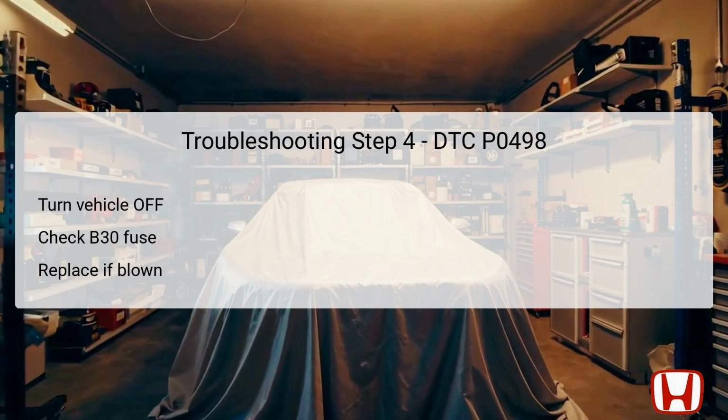If this fuse is found to be blown, replacing it is the immediate action required. However, if the fuse blows repeatedly after replacement, it is essential to investigate further for underlying issues, such as a short circuit within the B30 fuse circuit. Understanding the fuse's role in protecting the electrical components in the EVAP system is essential, and proper inspection of this fuse can often resolve the P0498 DTC quickly.